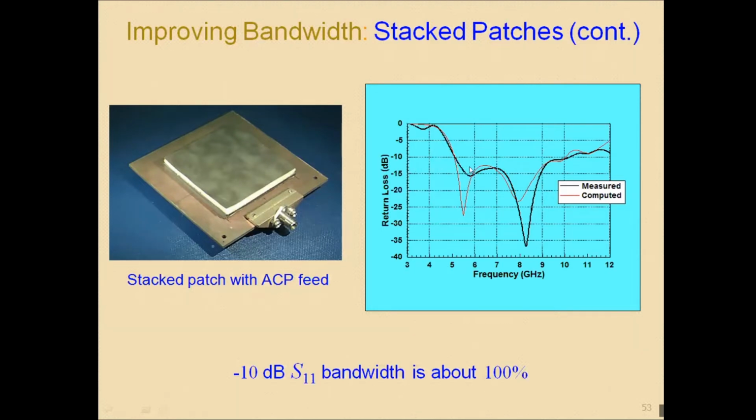If you draw a line at minus 14 dB, you see these frequencies from this point up to this point are below minus 10 dB, or minus 14 dB. When it is less than minus 14 dB, the antenna is working, meaning 95% of the transmission is possible and only 5% is reflected back. That is the meaning of below minus 14 dB.